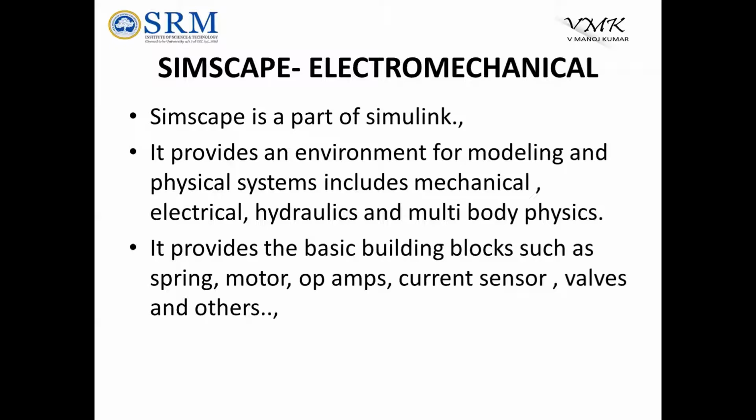So this Simscape is going to provide basic building blocks such as springs, motors, op-amps, current sensors, circuits, and even multi-body physics. Multi-body physics is a high level physical environment where I'm going to show walls, op-amps, drilling bits, everything as a physical model. If a lift is there, I can show you how it's going to work. I can simulate it as a physical engine in my Simscape.